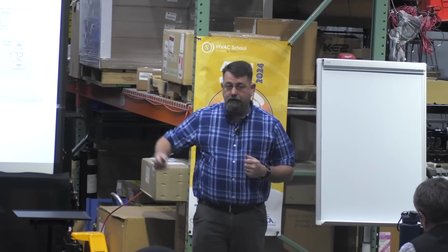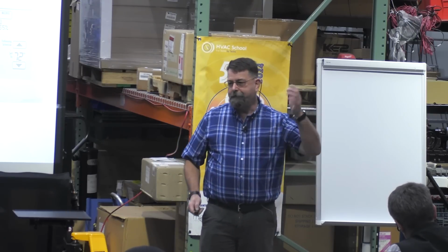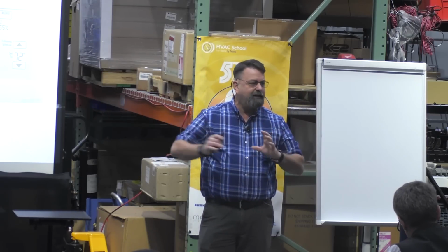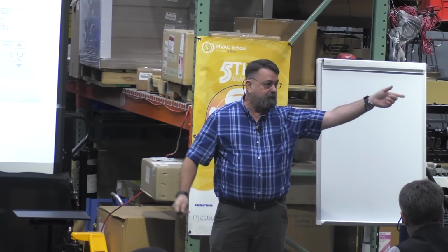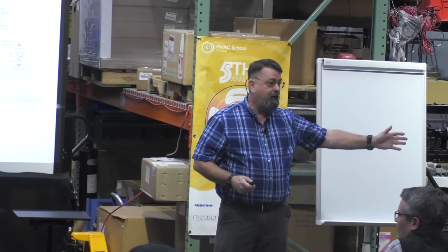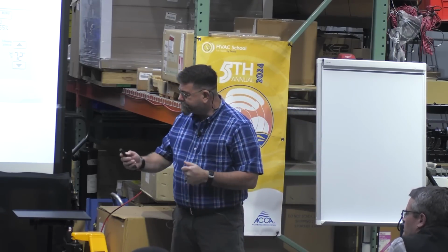And I can have a lot of these modules. I can have a bunch of them, right? I'll have one for my condenser. I'll have one driving my compressors. I'll have one running all those cases. I'll have one running defrost systems. So that side gets complex. But if I break it down into the basic function of this thermostat, it's exactly what it's doing, right? It's reading 40 case temperatures, but I'm only really concerned with this one that's running warm. I can break it down just like a thermostat. It's one input. There's a program in there that's telling it what to do because of that value, and there's one output. I'm turning on that case, right? So if I break it down simply like that, it works the same way.